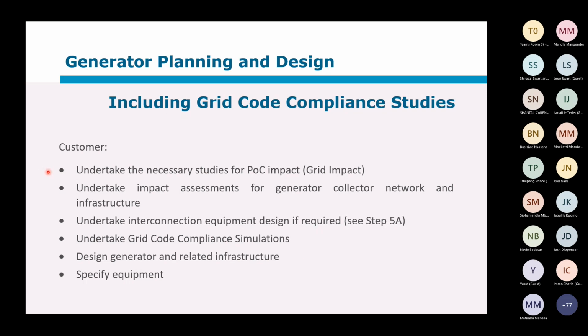So the customer would, firstly, there's also, again, and he could do this in the first phase, a grid impact study. So he wants to know what happens at that point of connection so that he can see if, even if you accept it based on it's a 10 megawatt PV plant, you've already looked at this and you say, okay, my voltage change is going to be, let's say 1%, and that's fine.